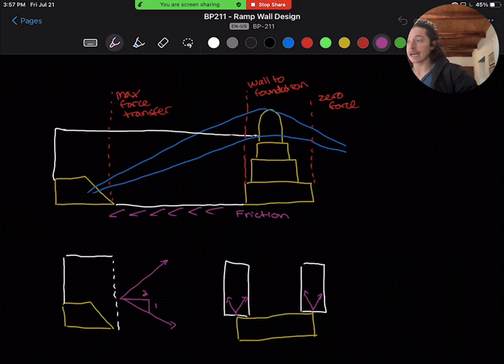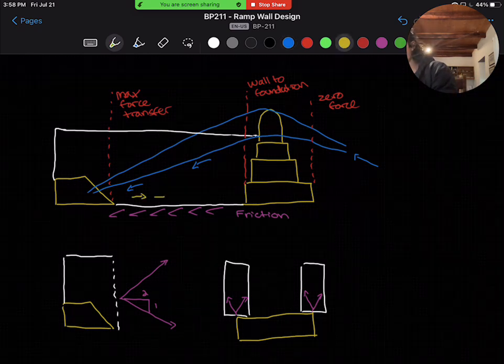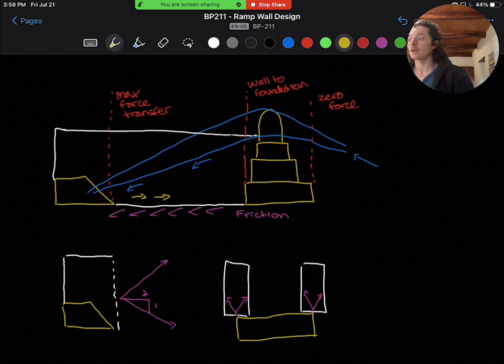Force flows from the cables into the gravity anchor beam. So when someone steps on the walkway, the suspenders will transfer this evenly between the walkway and handrail cables, and we'll get the force in the cables that travels all the way here into this anchor beam, which then in turn bears on the ramp walls, to transfer that force all the way back into the foundation and tiers.